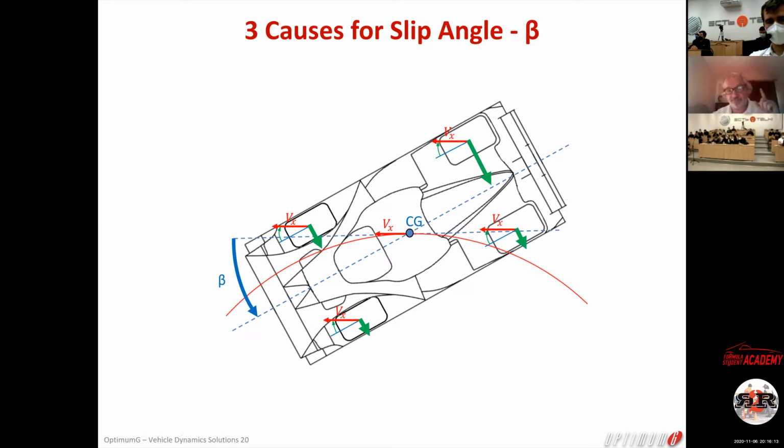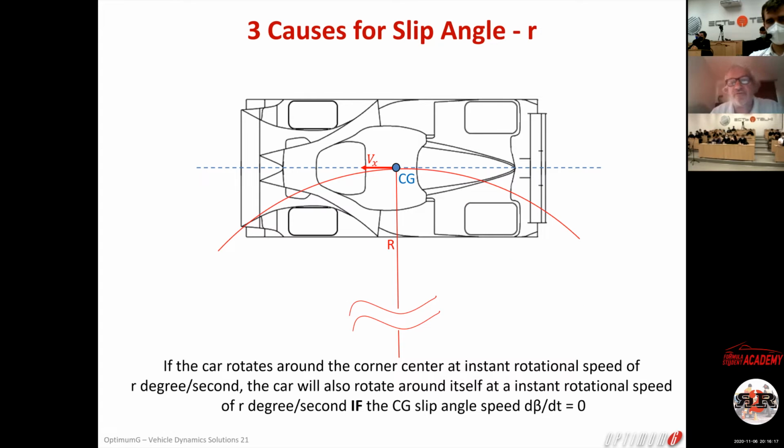And then, that's the biggest mistake that people make, they do not understand. You have a yaw velocity. You remember the car is like this and will be turning. So if the car is making 360 degrees in, let's say, 10 seconds, that's 36 degrees per second, okay? That you can measure with the gyro, by the way.